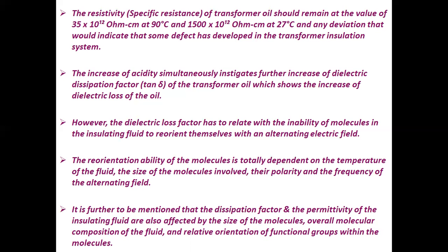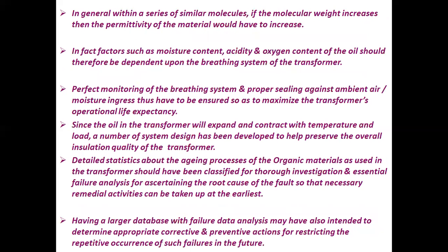It is further to be mentioned that the dissipation factor and the permittivity of the insulating fluid are also affected by the size of the molecules, overall molecular composition of the fluid, and relative orientation of functional groups within the molecules. In general, within a series of similar molecules, if the molecular weight increases, then the permittivity of the material would increase.